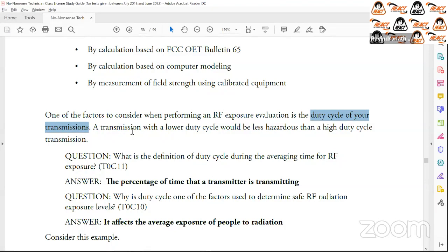Another way to think about it is, well, I don't know if we have any chefs in the audience, but if you use those hand mixers to mix batter if you're mixing a cake, right? Sometimes if you bother to read the manual, they'll tell you 2 minutes on and 3 minutes off, right? You may have other equipment like chainsaws and other things that will tell you like that, 2 minutes on, 3 minutes off. Things like pumps to pump up your tire pressure may say 1 minute on, 5 minutes off. What they're telling you there is the duty cycle.